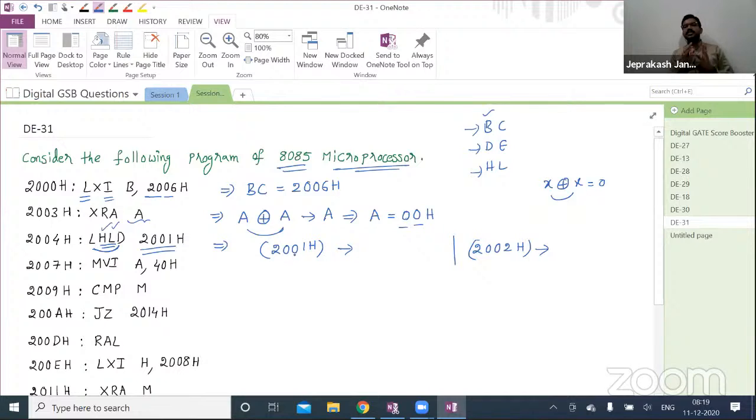So in this entire microprocessor, there is only one logic. Always the higher order memory location points to the higher order register. The lower order memory location points to the lower order register, right? Here you're having HL. H is the higher order 8-bit register, L is the lower order 8-bit. So in this memory location, whatever 8-bit data you're having will come here in this particular register. Similarly, the 8-bit content of this other memory location will come here.